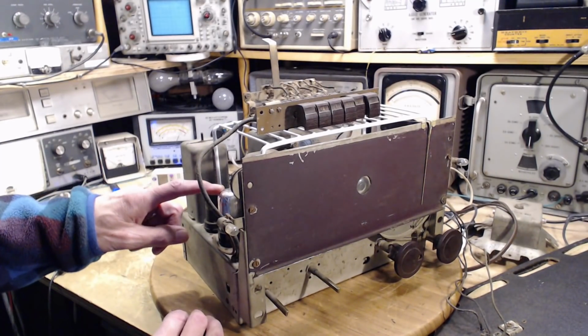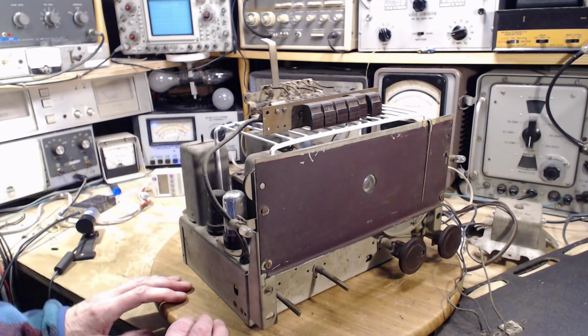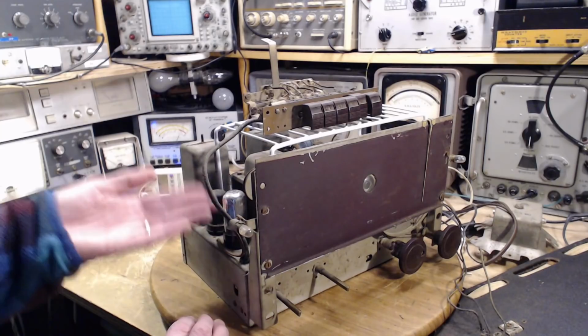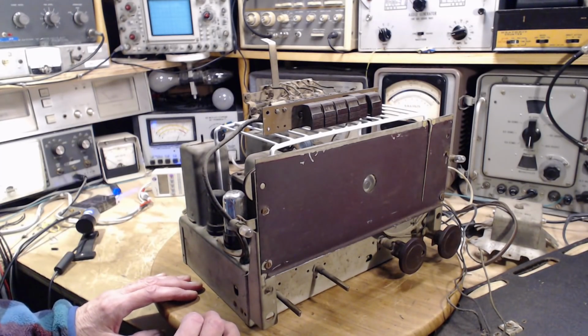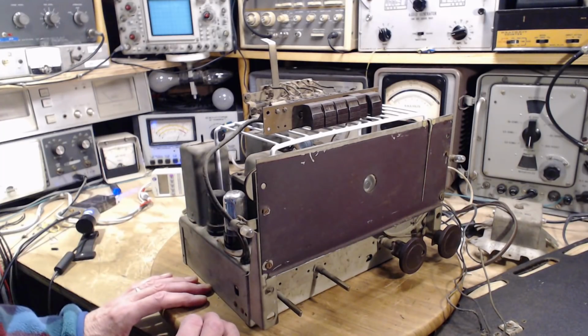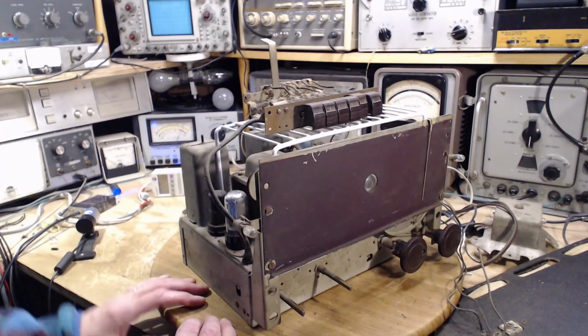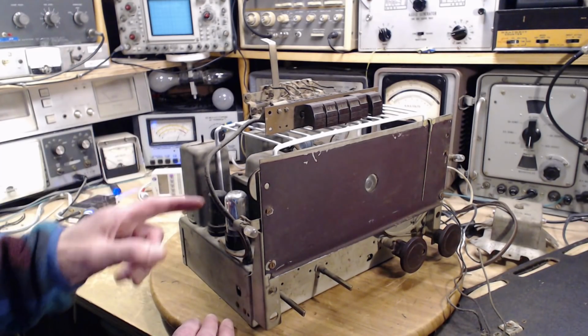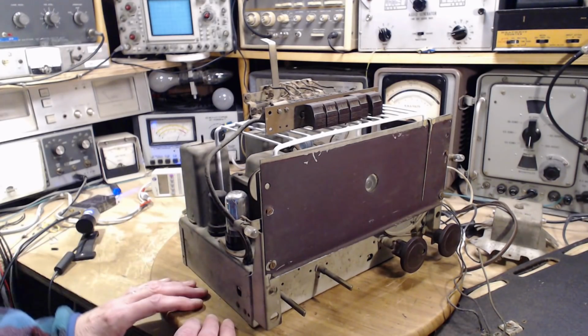One is it has a 6K6 output tube in it, when the radio is really designed for a 6F6. 6K6 should work okay, but there's better choices. 6F6 would be a better choice. 6V6 is probably a much better choice. 6V6 is more similar to a 6F6 than a 6K6. So this could be causing the distortion right here.